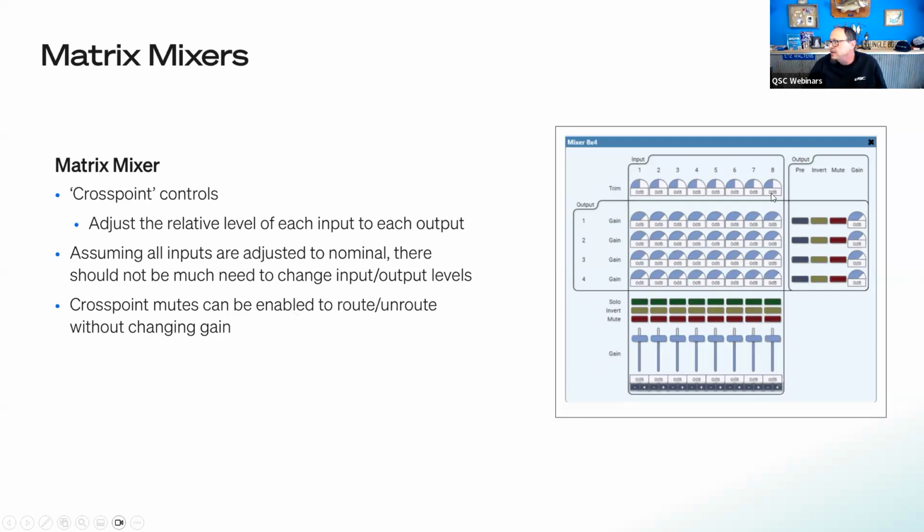Cross points are set. You can also go into the properties of a matrix mixer and add mute buttons if you want. But cross points set to 0 enables stuff to go through there. One of my key elements, and this is a generalized statement: if someone sends me a conferencing file and says, I'm getting this problem, and I open their matrix mixer up and things are at -12, -13, 20, -28, +6, if that matrix mixer is all over the map in the cross points, then the problem is somewhere before there. Someone didn't set the input gain to everything to be uniform, right?